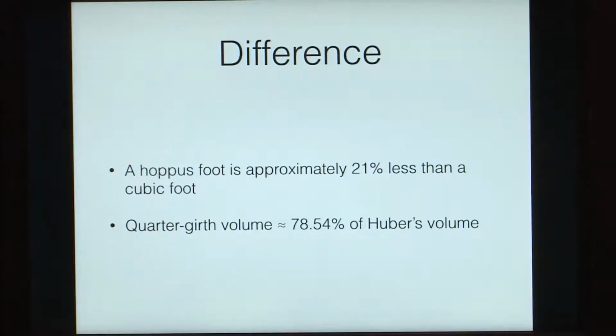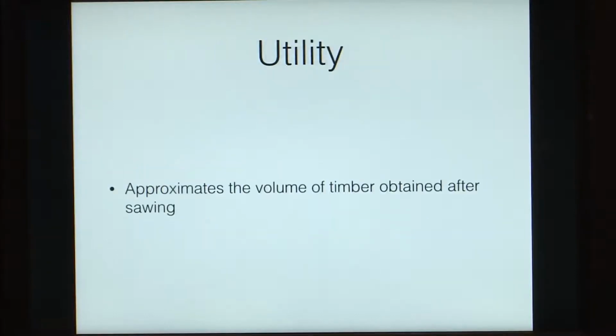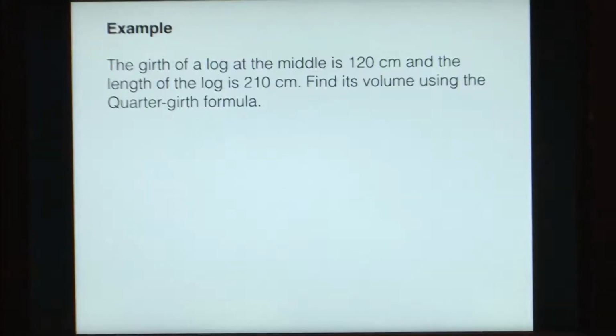Huber's volume is computed from Huber's formula, as we saw in the previous class, and its utility is that it approximates the volume of timber obtained after sawing. So, how do we use this formula out there in the field? Let us have a look at an example.